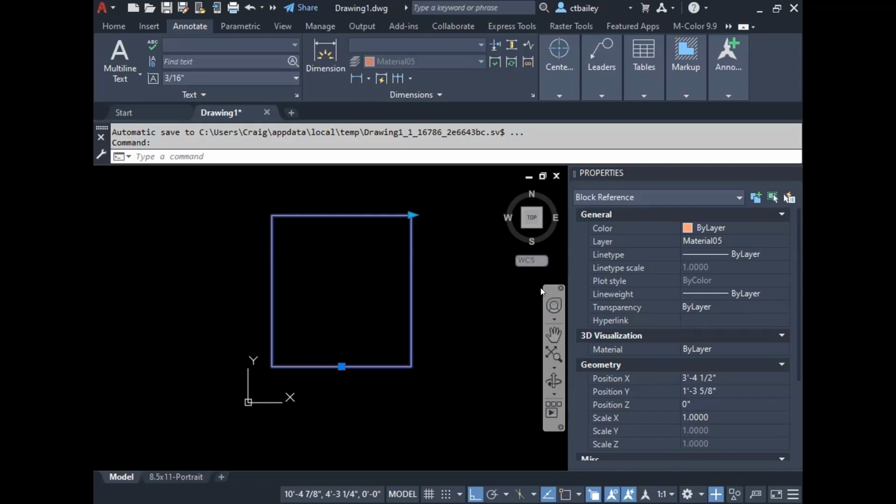Next thing I want you to do is take your command line and slam it to the bottom. Drag it up just a little bit. I want you to see 3 lines. Okay. Now, stretch action. Specify the parameter to associate with that. Now specify the first corner of your stretch frame. Start up here, go down a bit. I need it right there. Now click down there. Keep going. Have that segment fully contained within the box. These two segments are being split.